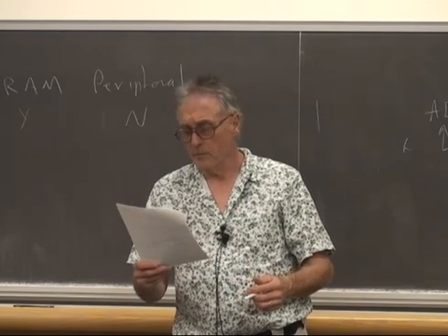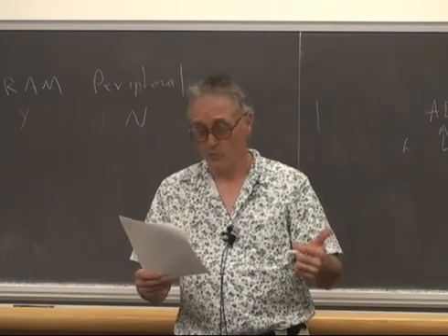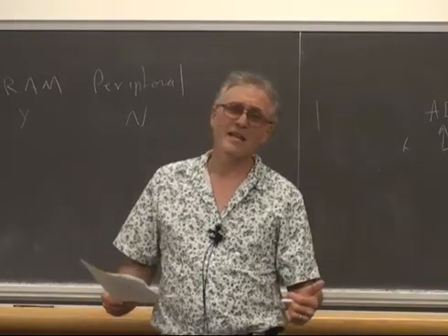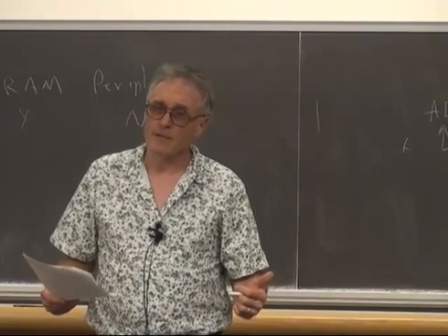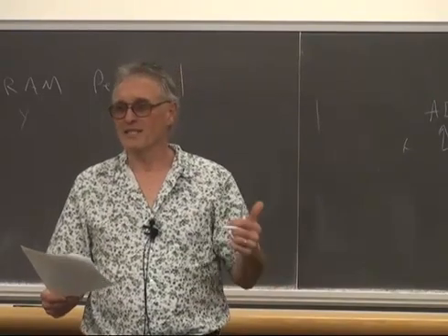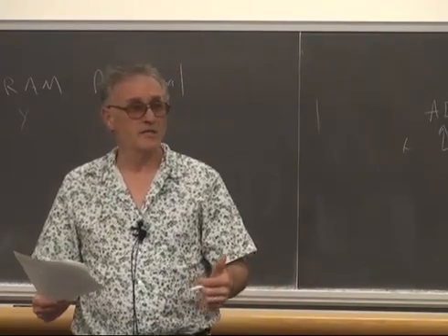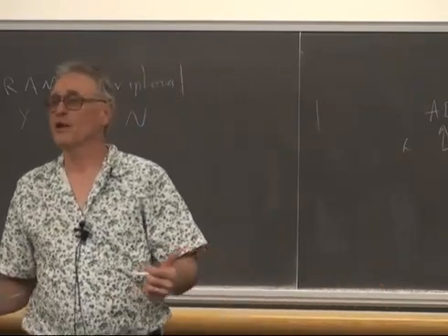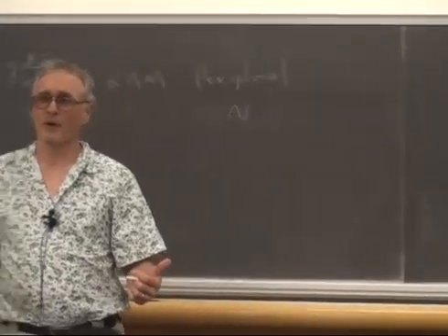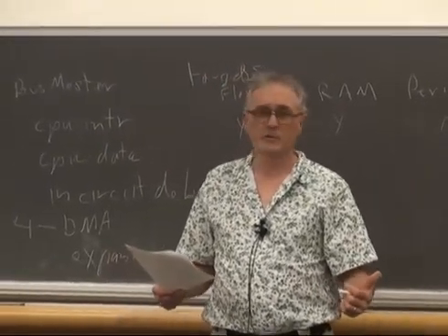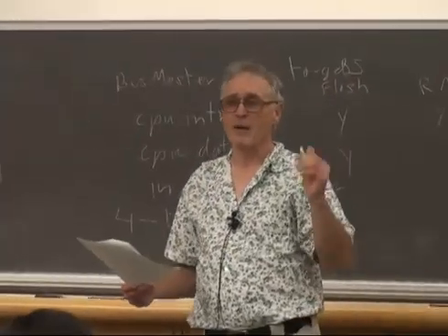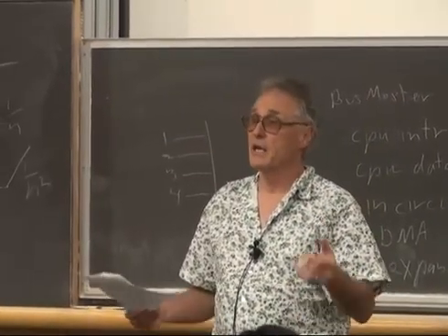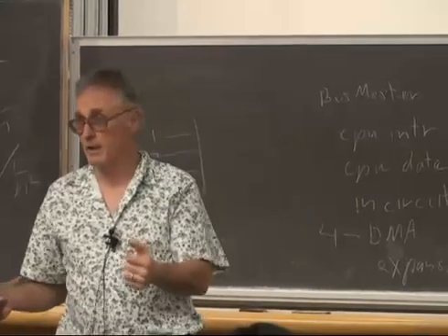You can generate interrupt events for done or abort, for source empty or source half empty, or for destination full or destination half full. So you can get early warning of when you're filling up the buffer due to a DMA burst. That would be a case where the DMA channel would interrupt the processor and say, you've got to do something, we're running out of memory here.